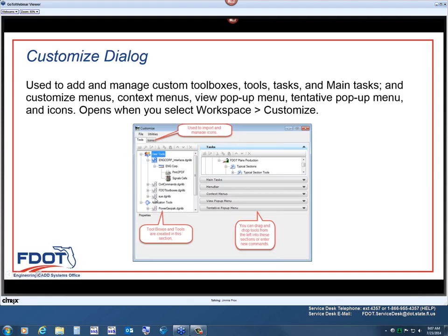You'll notice that all of the other ones that get delivered are grayed out, they're read-only. You actually have to open up that DGN lib and create the content in there, and when you open it up, then it'll highlight that in color and give you the ability to add content.